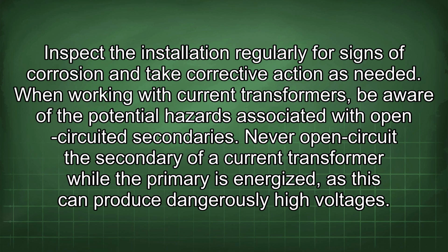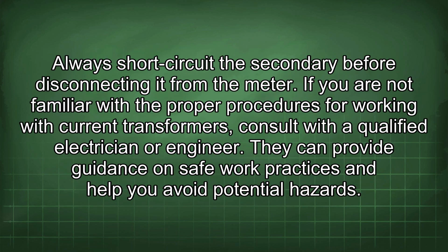When working with current transformers, be aware of the potential hazards associated with open-circuited secondaries. Never open-circuit the secondary of a current transformer while the primary is energized, as this can produce dangerously high voltages. Always short-circuit the secondary before disconnecting it from the meter.